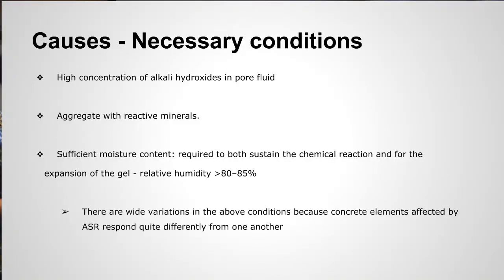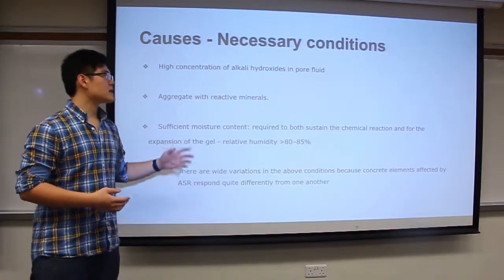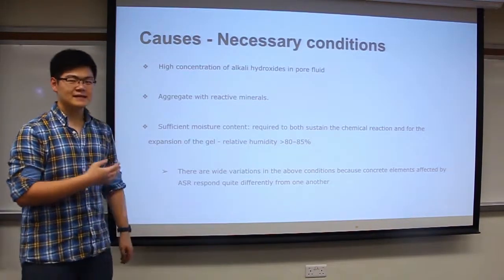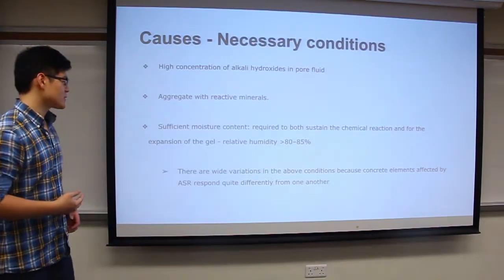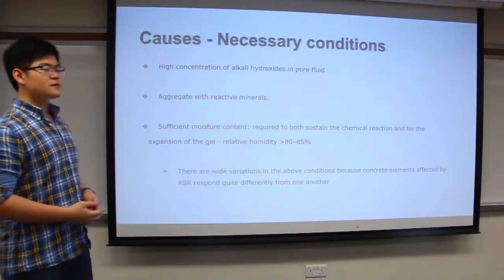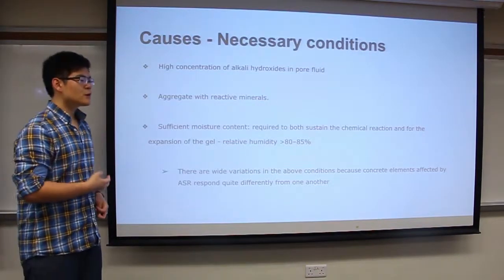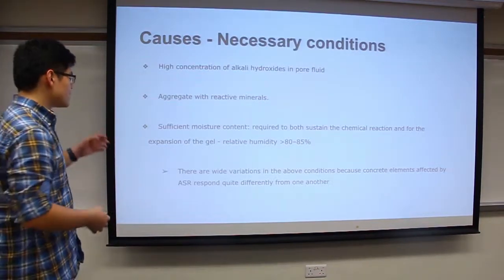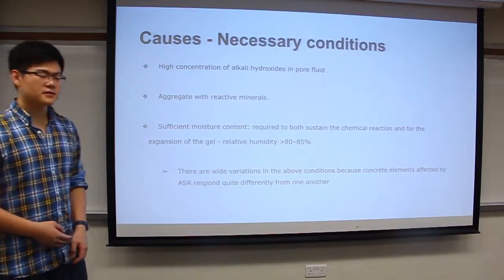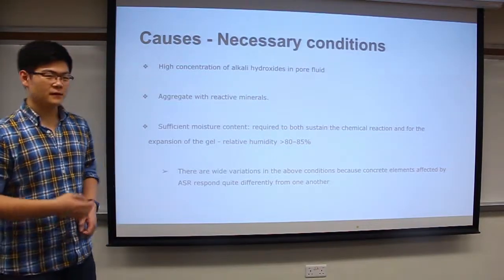And here are the necessary conditions of the ASR concluded from the principle. First, high concentration of alkali hydroxide in pore fluid is needed. And second, there should be aggregate with reactive minerals. And finally, sufficient moisture content should be present to both sustain the chemical reaction and for the expansion of the gel. But it should be pointed out that there are wide variations in the above conditions because concrete elements affected by ASR respond quite differently from one another.